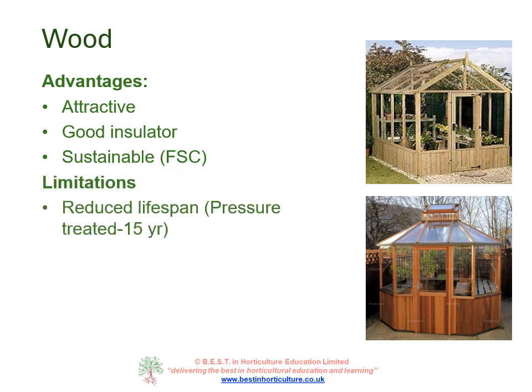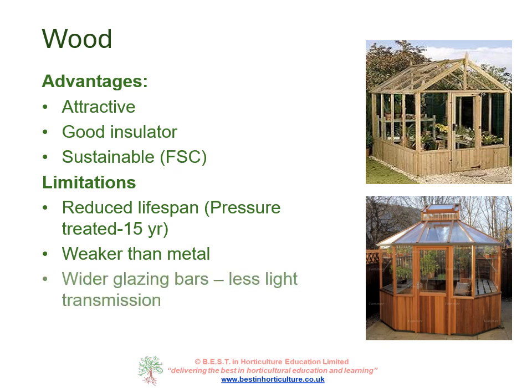Limitations include a reduced lifespan. For example, pressure-treated timber will have a 15-year lifespan or thereabouts. Some timbers have a longer lifespan than others, for example, oak or cedar. Timber tends to be weaker than metal, and this means that we need wider glazing bars to sustain the weight, and also more struts. And this has, again, a knock-on effect of less light transmission. There's also the need for rather more maintenance than would be associated with a metal structure.